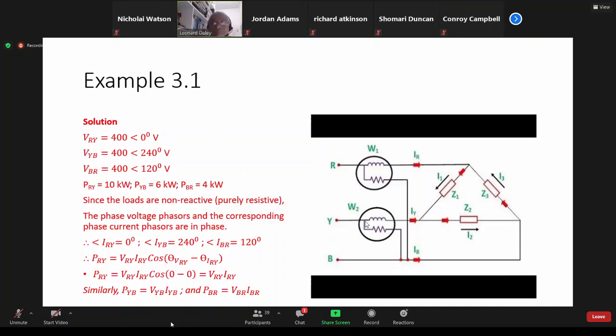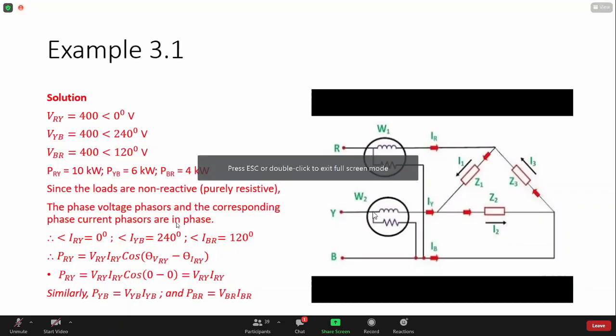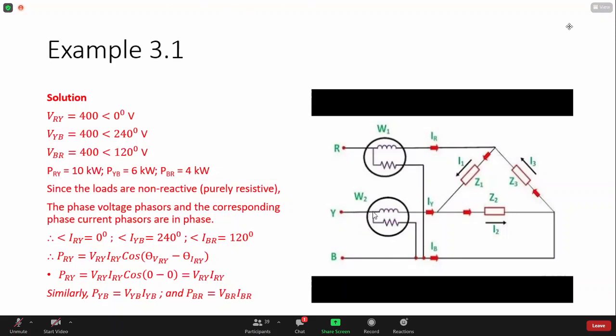And the voltage coil for wattmeter 2 is connected between Y and B. All right, so we know that Y is at the positive potential, B is at the negative potential. Y is at the higher polarity, B at the lower polarity. So we need VYB, but we know that already because we have defined that from before based on our phase sequence. So we have defined certain voltages already, VRY, VYB, and VBR. Now, wattmeter 1 said, well, we need also VRB.